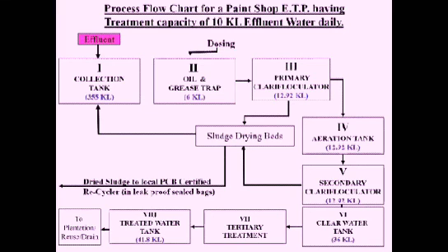From here, after dosing the chemicals in sufficient quantity, we send the effluent to the primary clariflocculator, wherein there is a conical chute at the bottom, and a slow stirrer, which helps the denser sludge collect at the bottom, and from the top we can have comparatively clearer water, since the precipitation, flocculation and coagulation has already taken place in this tank.